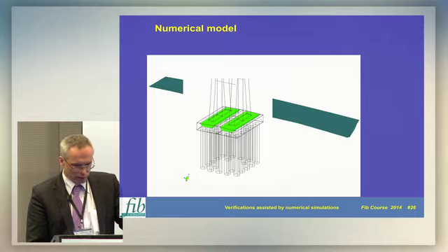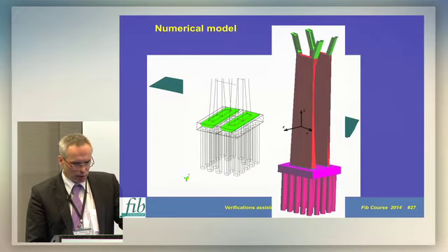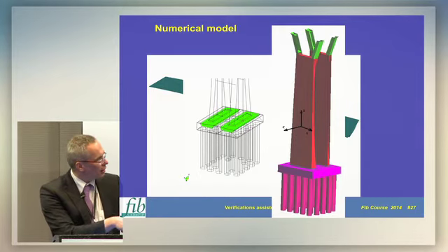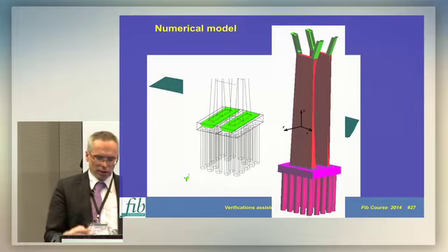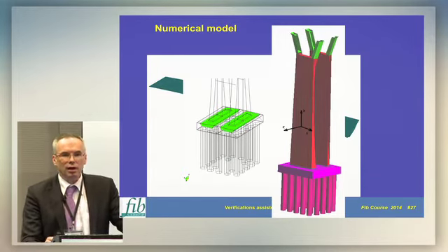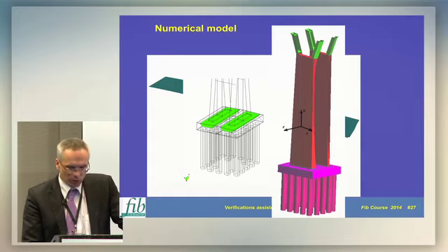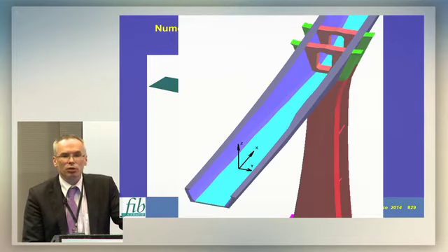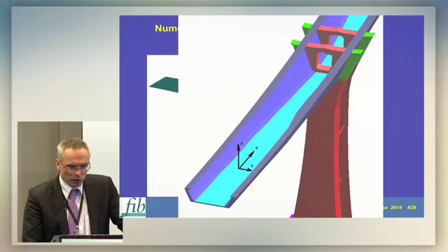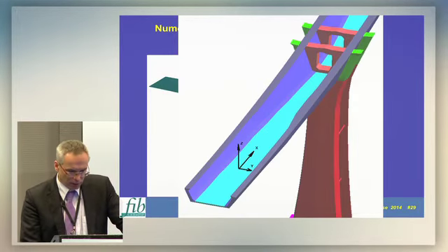Foundation, including the piles. These are the slender piers. To model them, we used shell elements. They look 3D, but actually by geometry they are displayed as 3D, but internally they are calculated as shell elements. Of course, to model such a large-scale problem, it is not possible to use solid elements for the whole structure, so it is important to make use of more efficient element formulations like the shell elements or plate elements.